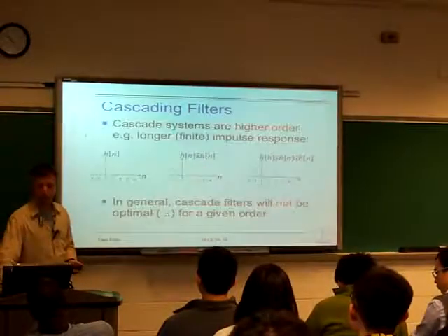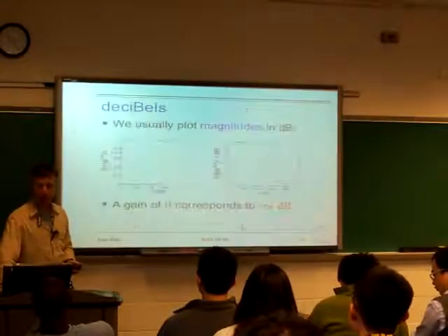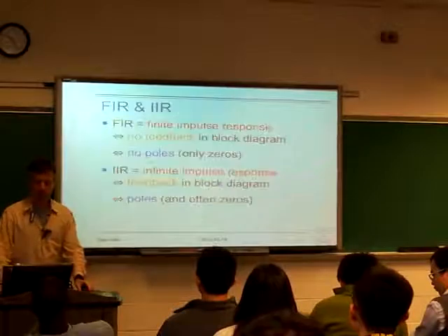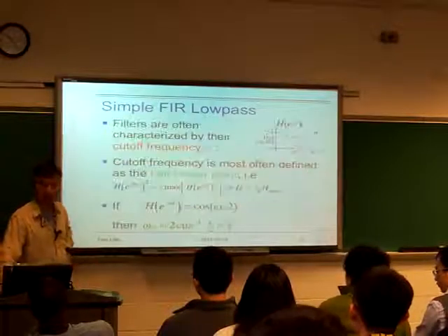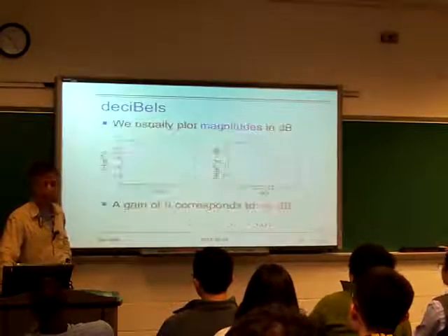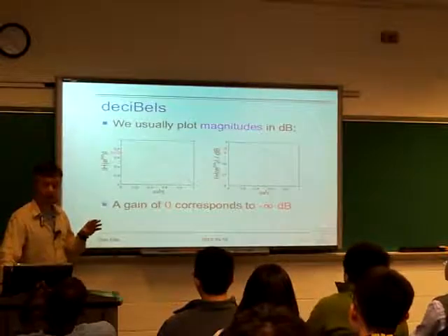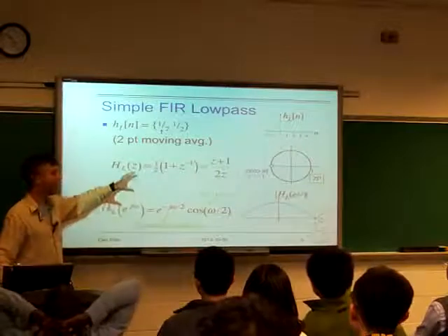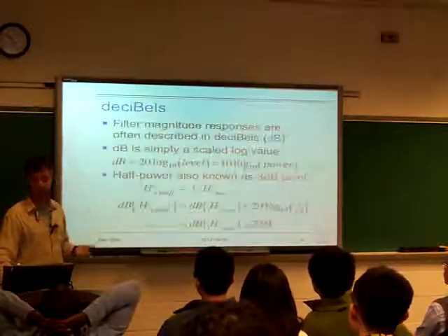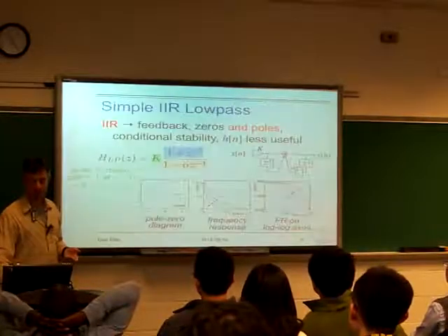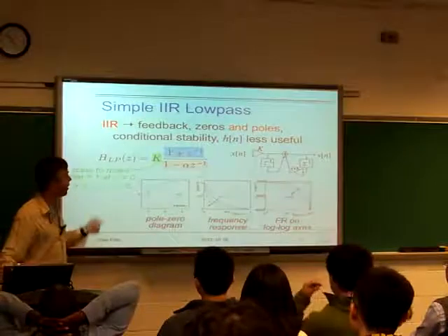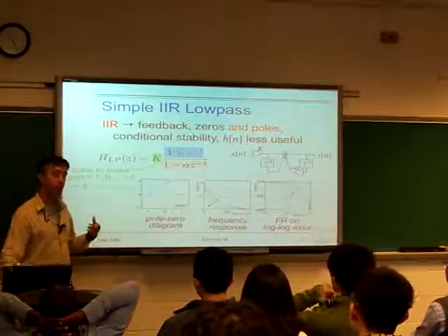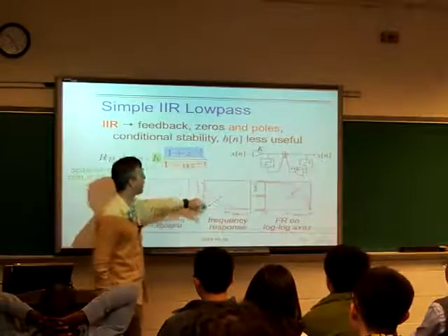In this slide pack we've spoken about a couple of very simple kinds of filters, just to get into the idea that a filter is typically a filter family, a set of, say, second-order FIR filters or two-pole IIR filters, which have a general shape, but the shape can vary.